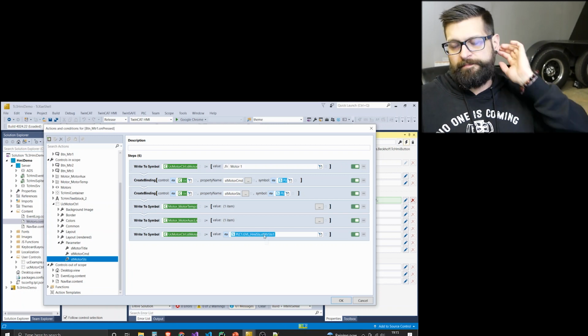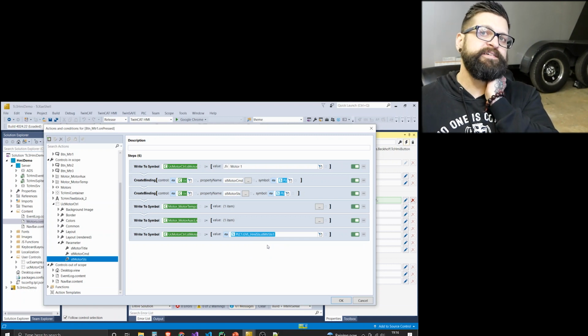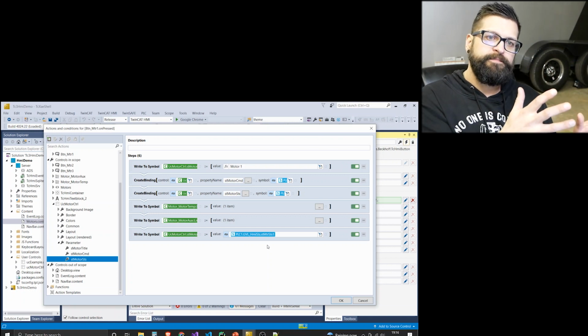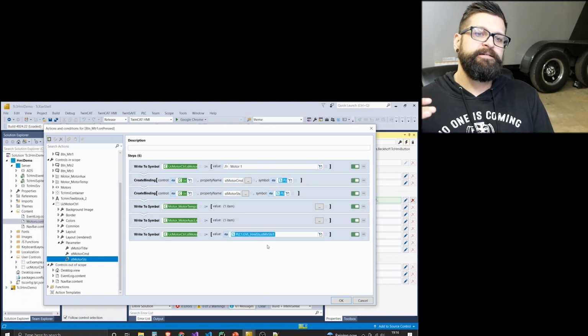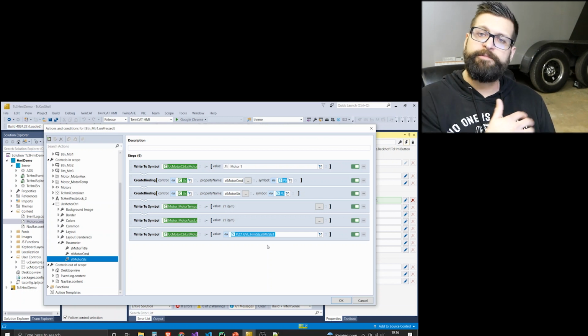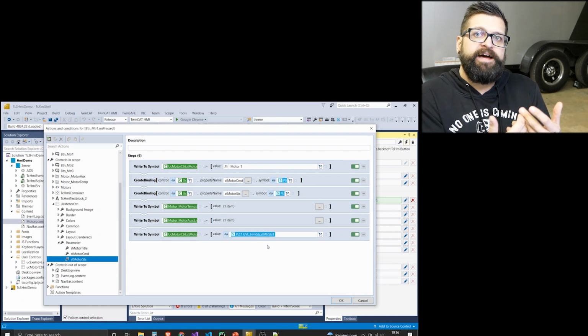And I don't want that, because for statuses, it's not such a huge deal, but for commands, it is a big deal, because when I go from clicking button 1 and displaying the user control data for motor 1, when I click start and stop, I only want that to act on the PLC variables for motor 1. And so I need a pathway back into the PLC, and you can't do that by value, right? Because when you're passing by value, you're just saying, hey, this is the active value for the structure. I'm going to pass this into this